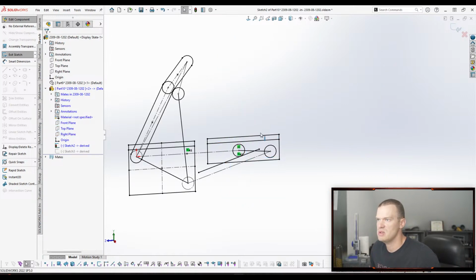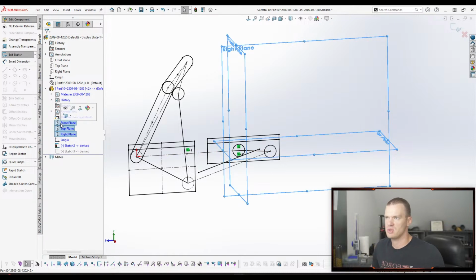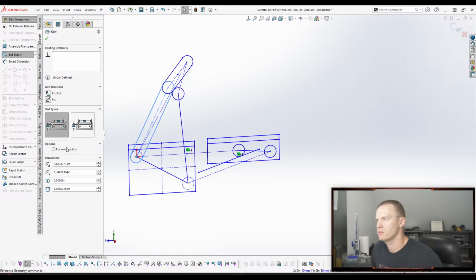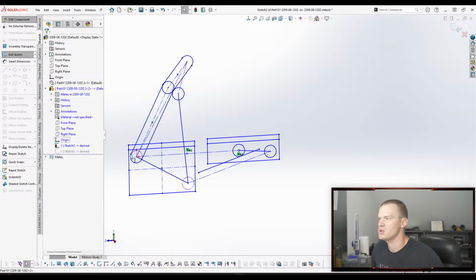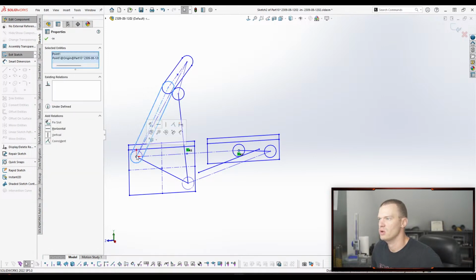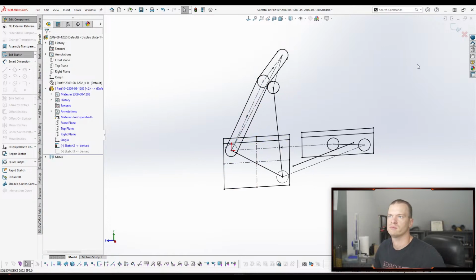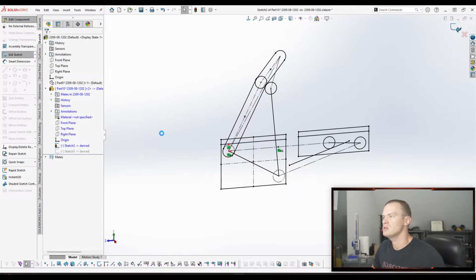So this would be the second way of doing it, where your base planes are more useful. But when you go to add them into an assembly, you'll actually have to go in and create mates, as opposed to all of the geometry snapping into place when you go to import them into an assembly. All right, so let's do this, right?